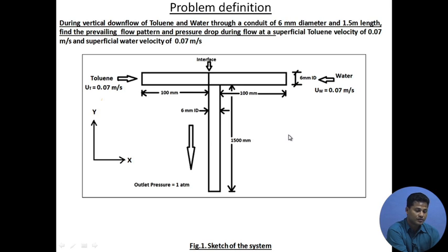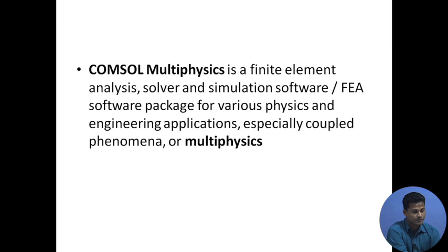The thing we will be doing is that we do not know what flow pattern will occur in this condition, and also what the pressure drop across this conduit will be. So, we will be utilizing COMSOL Multiphysics, a commercially available CFD software, and we will be getting our results with the help of that. I will be assuming a 2D geometry.